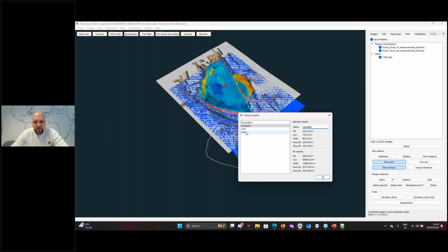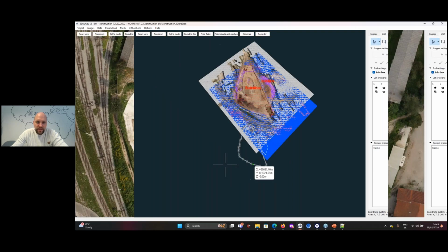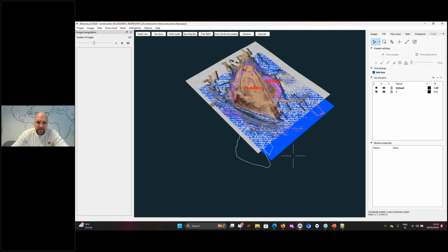And number 3 and 4, we will just delete. These are because I loaded DXF twice, so we have 2 lines. Okay, so I should actually go to CAD, select this line and press delete. It's deleted, and go here and delete the duplicate of that one as well.